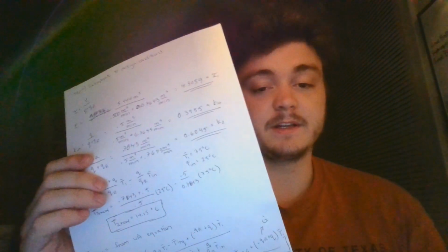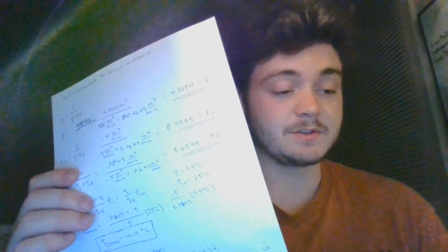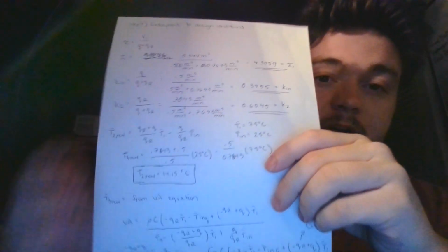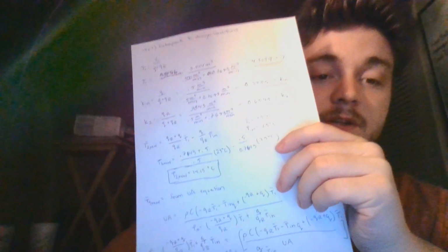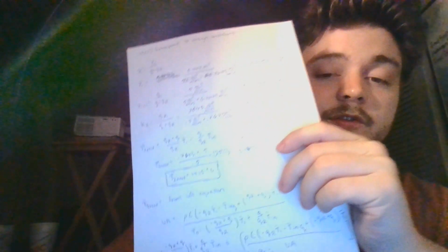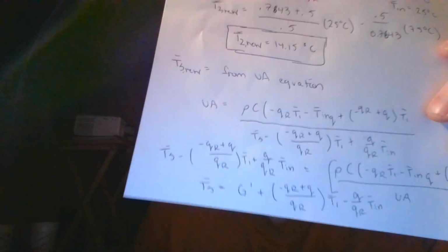With all of this information, we were then well on our way to designing this process for our PI controller. In order to finalize these values, we had to do a controller tuning, which was important for finding the ultimate gain and the time constant associated with this.